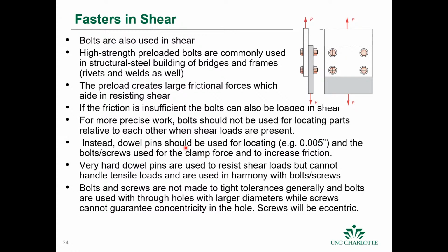Okay, so dowel pins are helpful because they're very hard and they can resist the shear loads, but they can't handle any tensile loads. And also, it's very important to note that bolts and screws are not generally made to tight tolerances. Okay, and bolts are used with through holes. Okay, so you put the bolt through the hole, and the hole is larger than the bolt. So it's not necessarily a good idea to use bolts to locate things in your design if you need any sort of high accuracy or high tolerance.